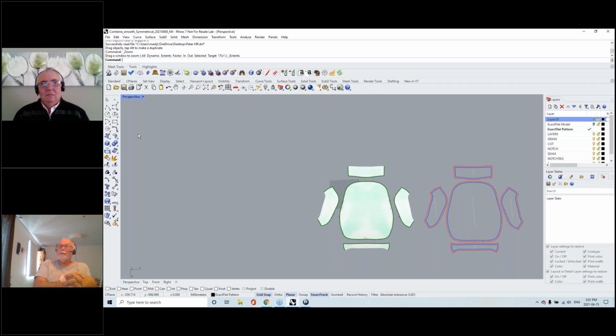And if it's a large object, there are ways to save money on targets. For instance, we have things called turtles, which are little stick-on target holders with 4 or 5 targets on them. You can take them off after scanning and reuse them on the next thing you're scanning.